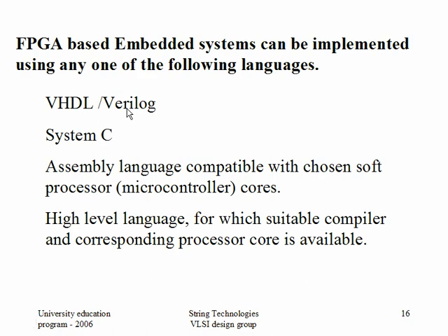VHDL, Verilog. Of course, SystemC is also a hardware description language, but languages like SystemC and SystemVerilog are considered to be at a higher abstraction level. VHDL and Verilog allow you to code at what is called the register level. But in SystemC and SystemVerilog, most of the time we write superficial code. SystemVerilog is somewhat similar to C++; we go by an object oriented mechanism. We don't talk at the register level. But in VHDL and Verilog, you are working at a slightly lower level. That's why they are different.